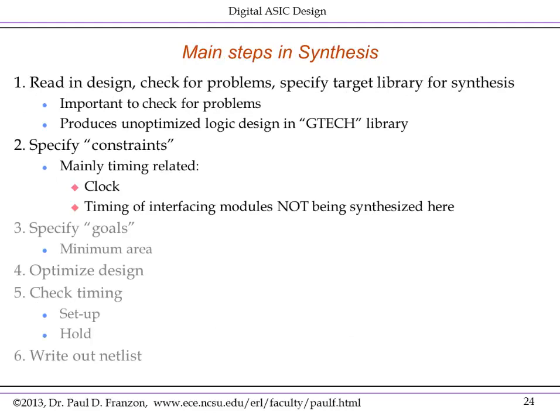So again, what we've just been through are the two first main steps in synthesis. The read, which also analyzes the design, tells you what are flip-flops, what are latches, and tells you about any potential problems in the design. The next step will specify the constraints. All the constraints here, and all the constraints in general, will be timing related ones, particularly what are the clocks, their period and skew or uncertainty, and what are the delays associated with the part of the world that's not part of the design that I'm actually synthesizing here.